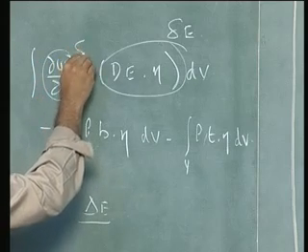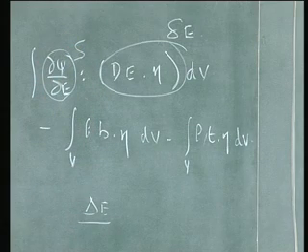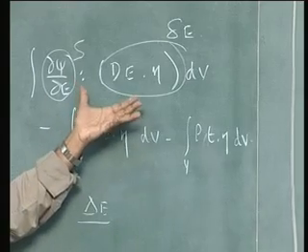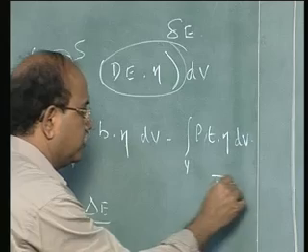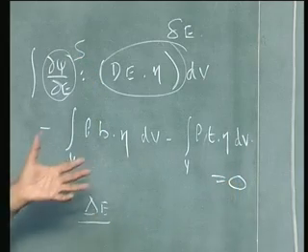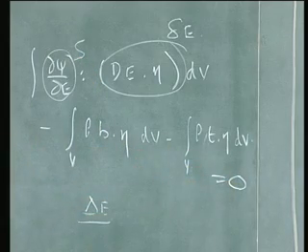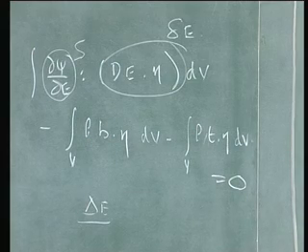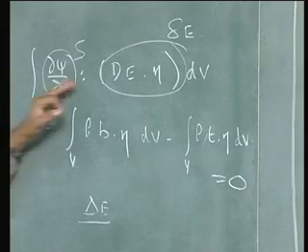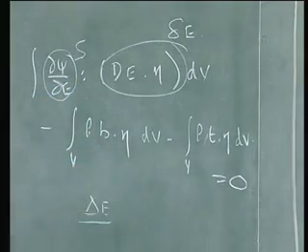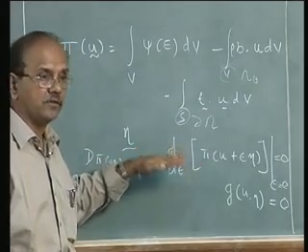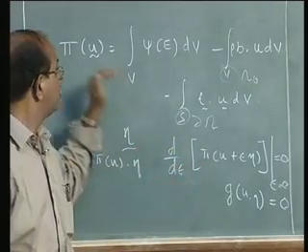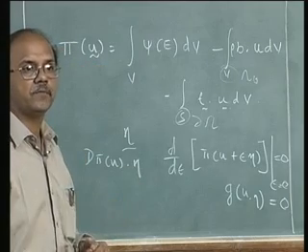In fact, this would give rise to what is called the second Piola-Kirchhoff stress. So the first term is the internal virtual work, and the second and the third terms together give rise to the external virtual work. So in other words, this virtual work principle is the result of minimization, or the result of the application of the Gateaux derivative or directional derivative to this functional φ.